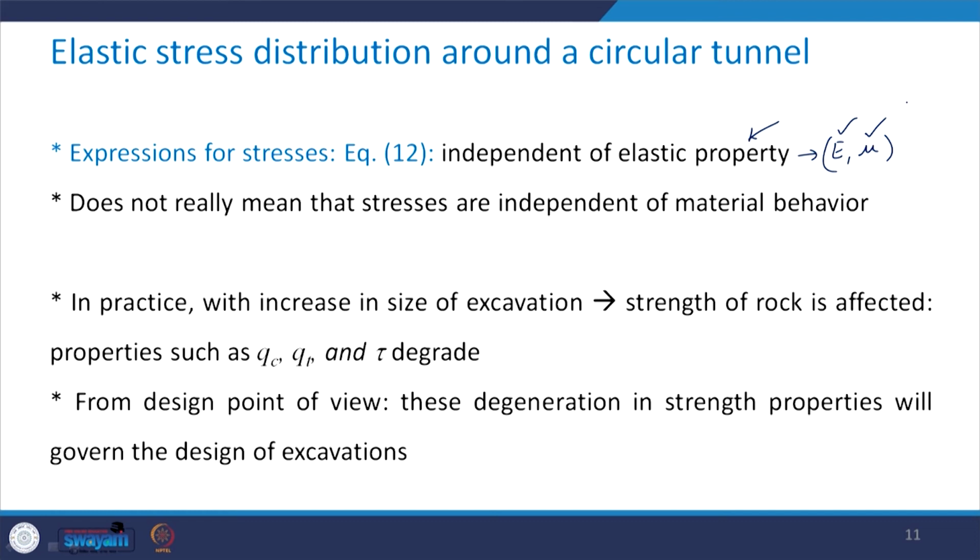What happens in practice is that with increase in the size of the excavation, the strength of the rock is influenced, and the strength properties such as UCS, tensile strength and the shear strength, they degrade. So, from design point of view, this degeneration in the strength properties will govern the design of excavation.